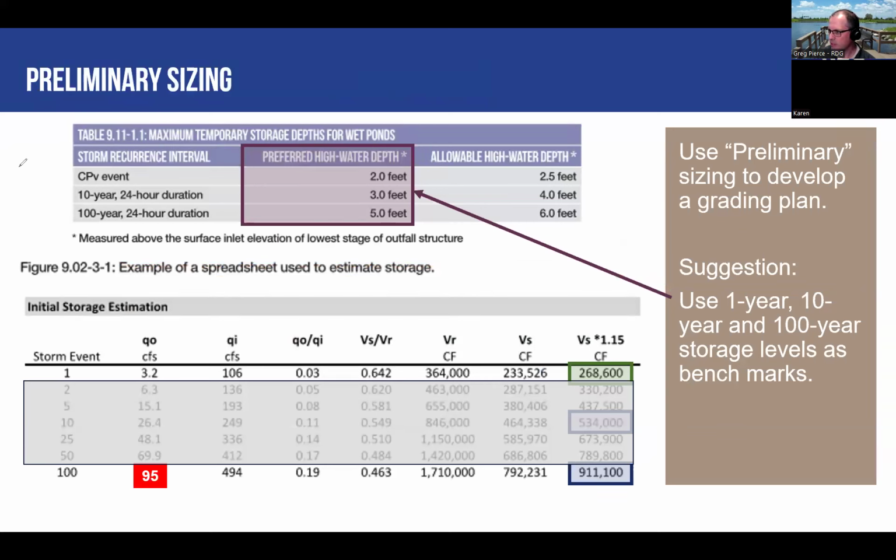So usually what I do is look at the stormwater manual and say, we'd like to limit our bounce to reduce erosion potential. We'd like to keep things for the smaller storms, the 1 year storm, at about a 2 to 2.5 foot level of bounce. That helps establish that vegetation better. If you have water that's getting 4 or 5 feet deep once a year, it may be more difficult to maintain the basin and keep the vegetation going and not have it eroded away on the shoreline. And then for safety, you may want to set some sort of high water limit, 5, 6 feet, what have you, to figure out how big your basin should be.